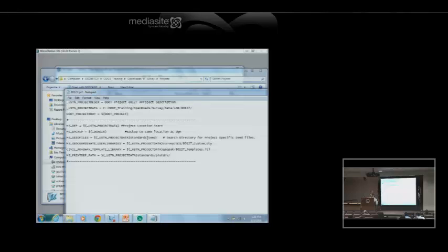Another thing that may be defined uniquely is a template library, so I'm pointing to one specific for the project there. And you may elect to make seed files specifically for the project that contain that grid-to-ground conversion. That's another thing that could be project specific.